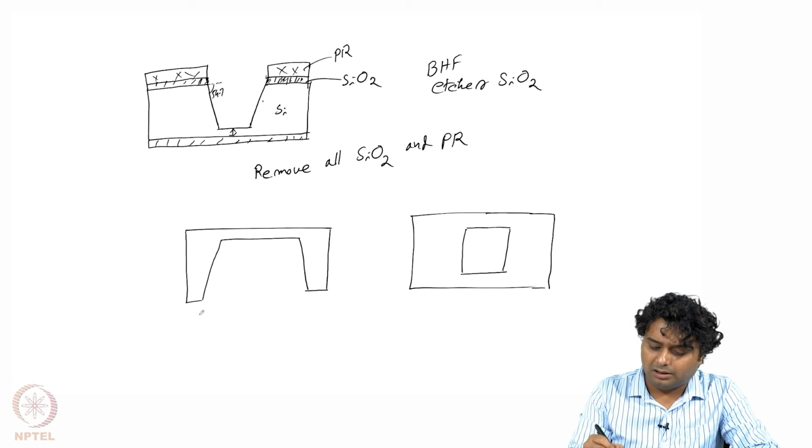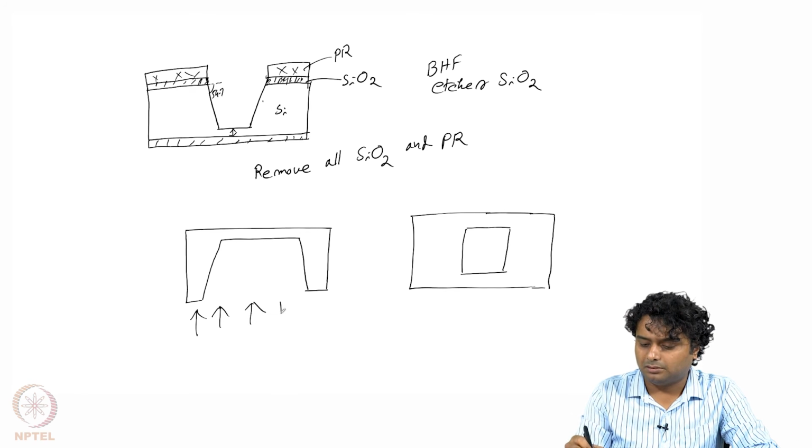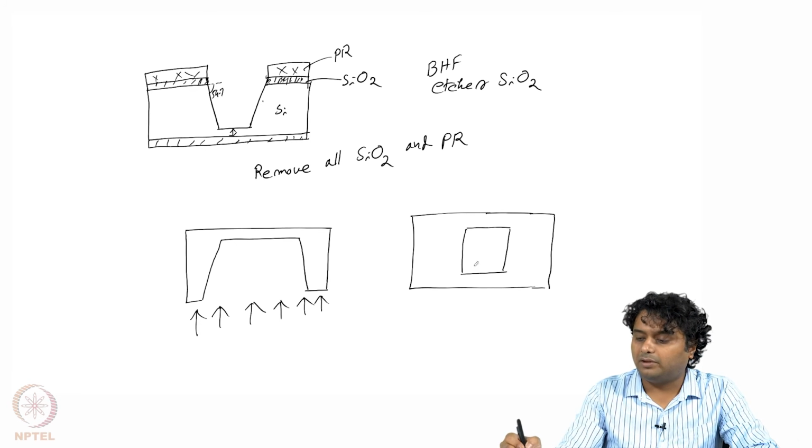So we irradiate this sample from the bottom, and then we can see the light coming out of the membrane, and like that we can identify the membrane. Then on top of that we can again put photoresist and do lithography to put all the piezoresistors.